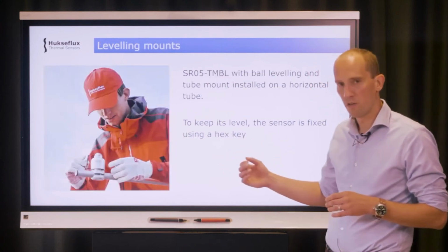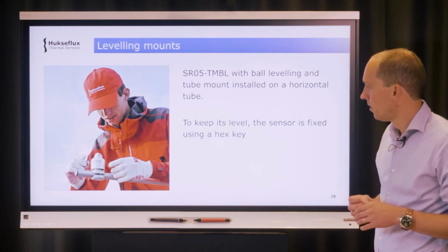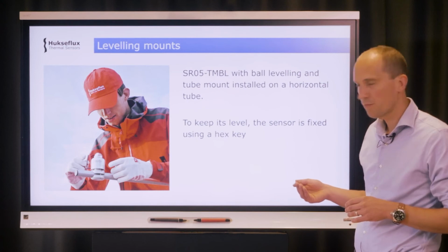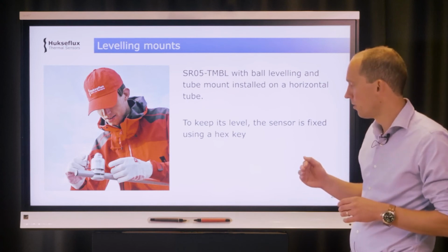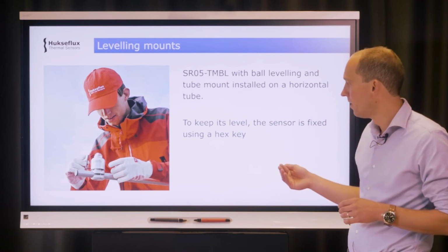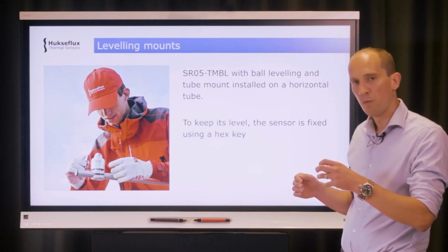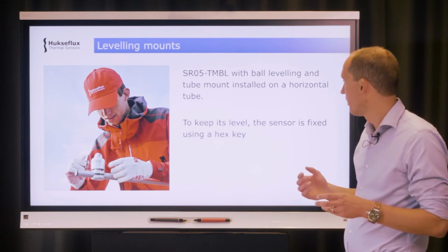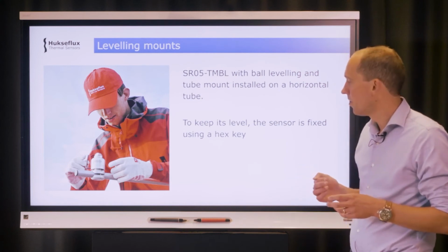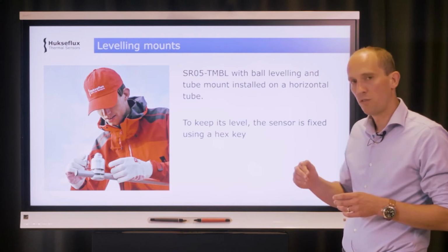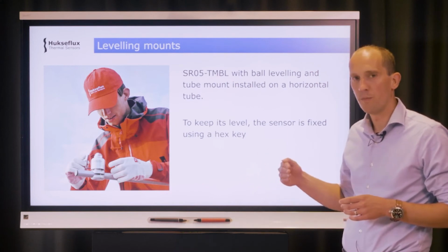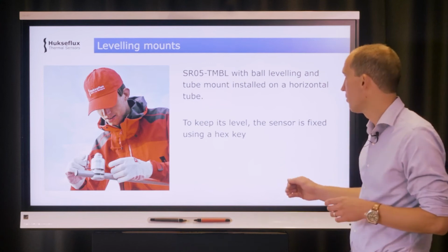And here you see a picture of the SR05 with a tube mount ball leveling option fitted to it. So you can actually install this instrument on a horizontal tube, set it level with the visual bubble level, and then fix the sensor level with a hex key. And these are examples of solutions for how you can properly install and maintain a long-term level of your instrument.